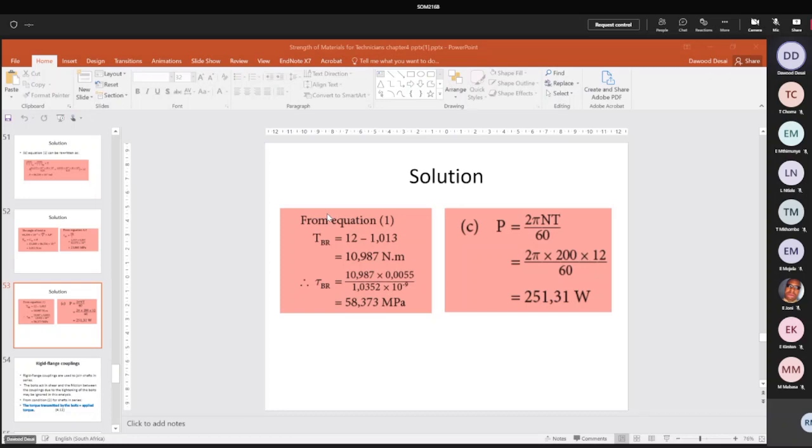Flat sheet of steel or any material, certain thickness, they bend it under heat around some type of a mandrel. A mandrel is like a die to give you your diameter. Then they weld along the longitudinal direction. You can see here you got stress longitudinal. And then they put end covers or end caps and they weld the end caps along the circumferential direction. And they have a small type of a hole somewhere where you can pump in your fluid or your gas or what. Okay, so that's how they do it.